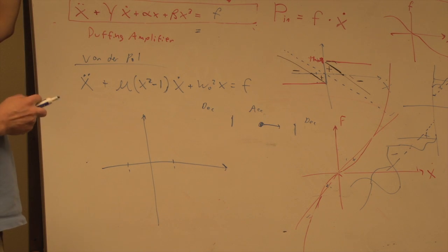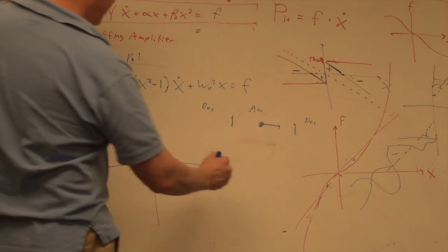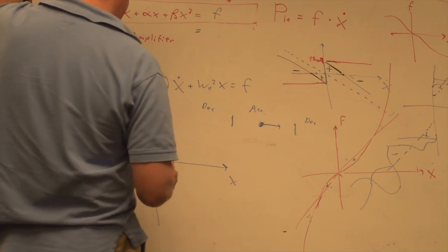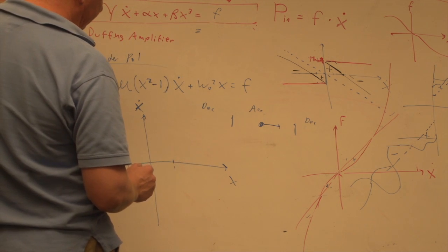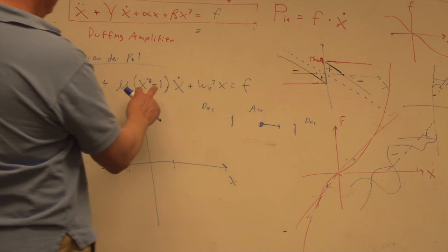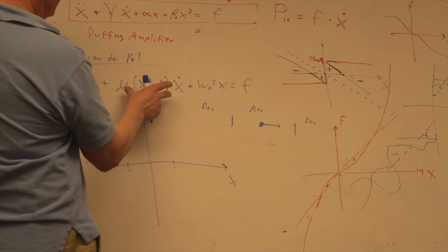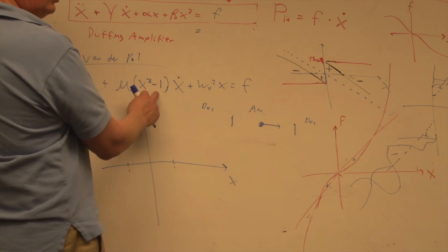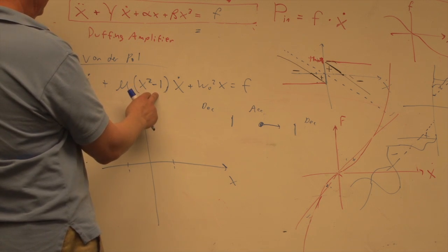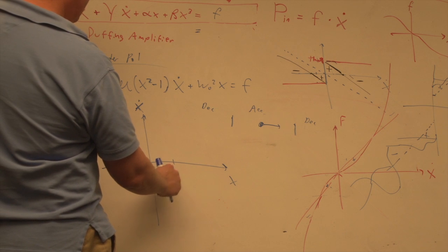Would that correspond to a bistable switch, where it draws you home, but when you get close to home, it pushes you away from the exact center to two stable locations either side? No, I mean it's not bistable. It's still just going to be an oscillator, because it's damping only, it's not the spring forces. Okay. So the way you just described that, I'm seeing the damper putting in energy. This is a damper when x is greater than 1, and it's a motor when x is less than 1. Okay.